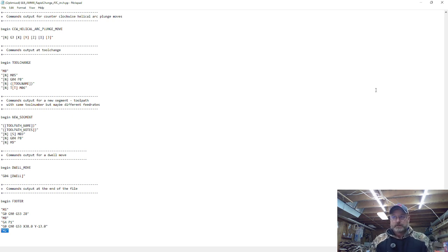So I guess in summary, you've got to get your post processor from Rapid Change. You have to get that into your software, Vectric or whatever software you're using to output your CAM files, and make sure those are working together. And then you have to get your macros from Rapid Change ATC, especially your TC macro. Make sure that is on your SD card. Then your post processor has the commands for M6, which will point it to your macros on your TC card.